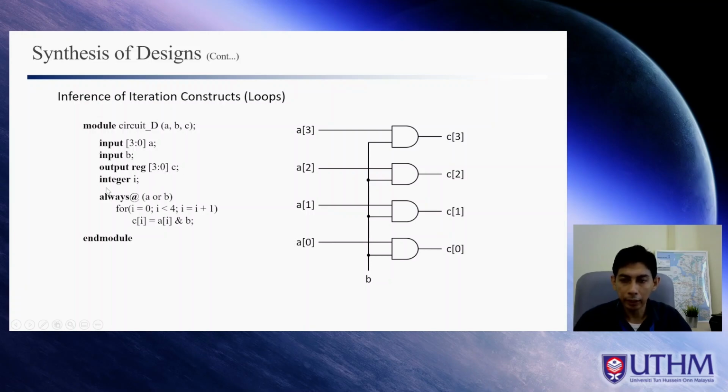And we have another variable, and it is declared as an integer I. Okay, look at this, for always, and again, this is an always block, so here should be behavioral code. And this is the sensitivity list. So for I equal to 0, yeah, this I, this will not be synthesized into any wire, right?